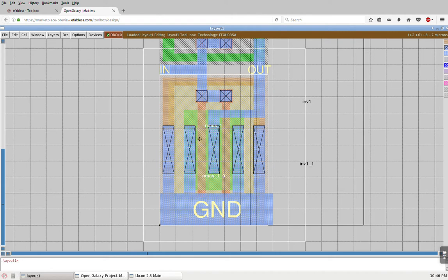So this area over here is an NMOS transistor. There's a second one over here, very easy to see. The big contacts over here, represented by essentially this big X, and the box over here is actually more than just a contact. It's a combination of N diffusion, contact, and metal. The cut opening is actually not exactly what you see here. It's going to be on the inside. There's going to be multiple contacts at GDS time, but it's a lot easier to see this way.